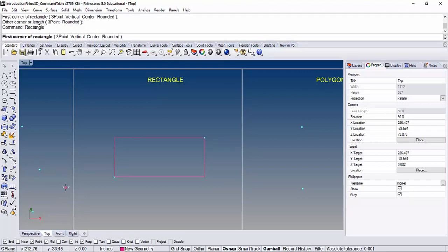Or if I type rectangle again, if I want to do a center rectangle, I could start to have a rectangle that's growing from the center, right? So in this case, I could say the length, let's say 2 values and height 3 values. So we can start to create also a rectangle this way.